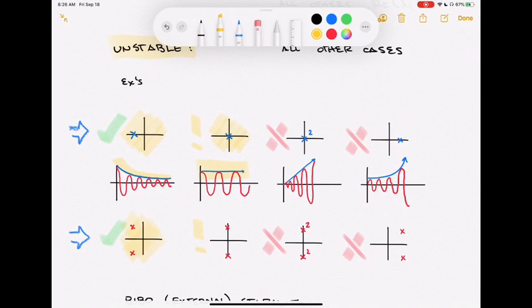If we moved it a little to the left, it would exponentially decay, right? But when we get it right on that omega axis, it's at that boundary point between decay and growth. It just holds the value. This is on the edge of stability, and they use a special term for that. They just call it marginal stability.